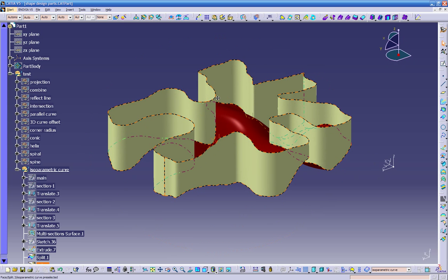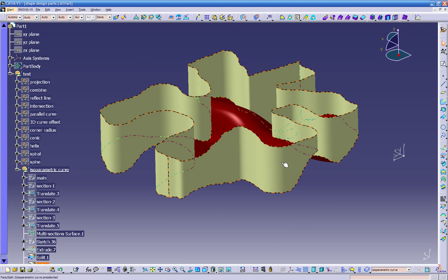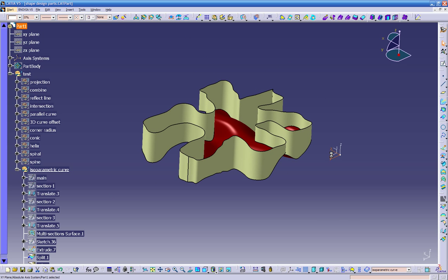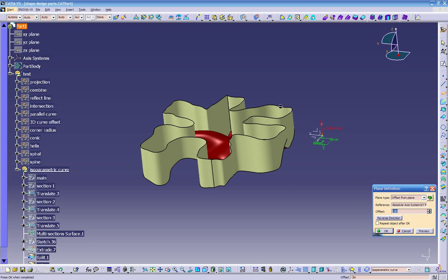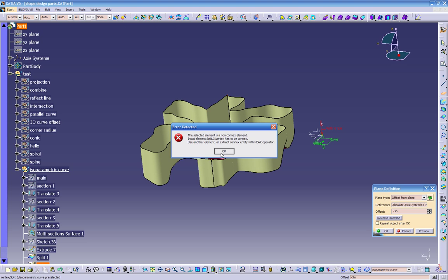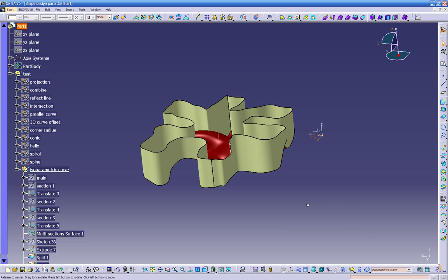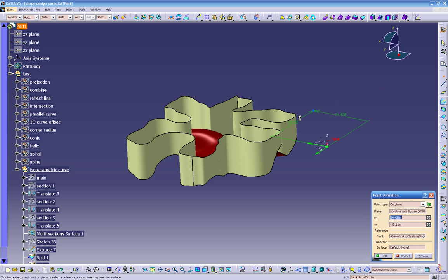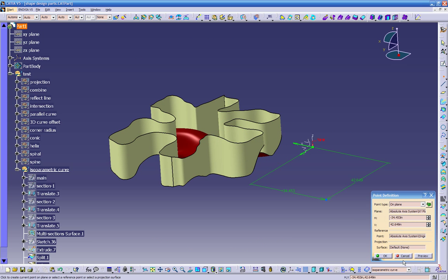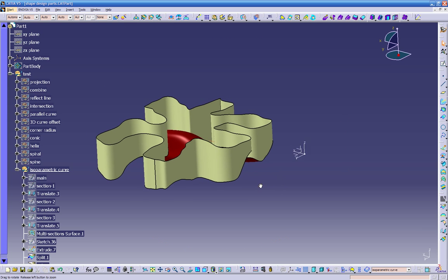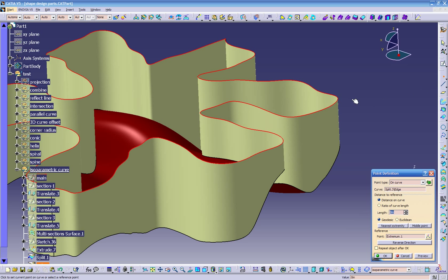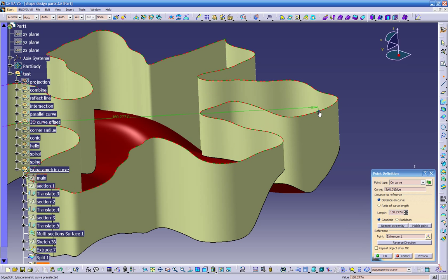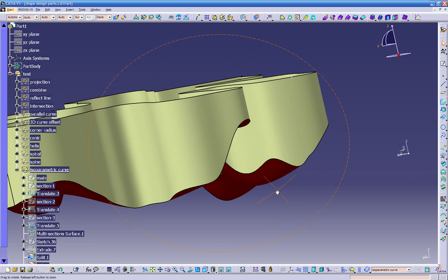And then if you want to cover the back over here, we can create another surface. So we can get the plane right now, we take a plane and we can move it to any of those points where it doesn't have a point. So in that case, we've got to create a point on any of those edges. Let's cancel this. Make sure we click on the curve first and then click on the point. So now we're going to create a point on the curve. And if you click OK, now we have a point on the curve.